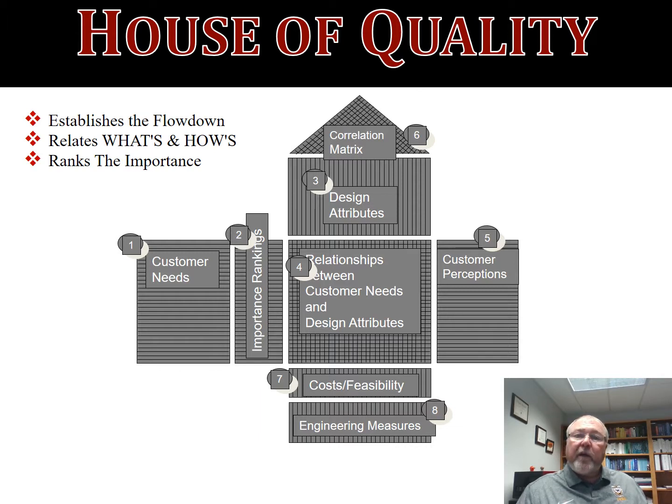When you have plus signs, what that implies is that there's some synergy that you might be able to leverage between the corresponding design attributes. On the other hand, if there's a negative sign, what that means is there's some disconsonance between the two, that there's some conflict, and that when you increase one, it will be to the detriment of the other. Anytime you have negative signs, what that implies is that you are going to have to make some determinations, hopefully driven by the voice of the customer, about compromises you're going to have to make when you design your product.